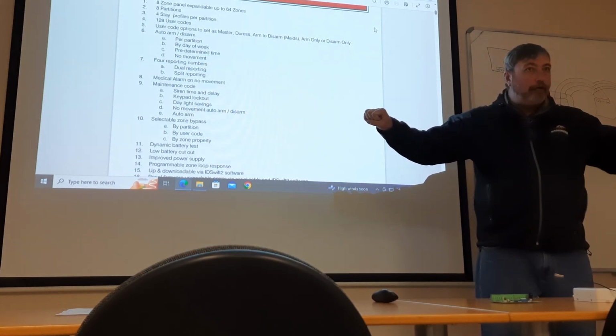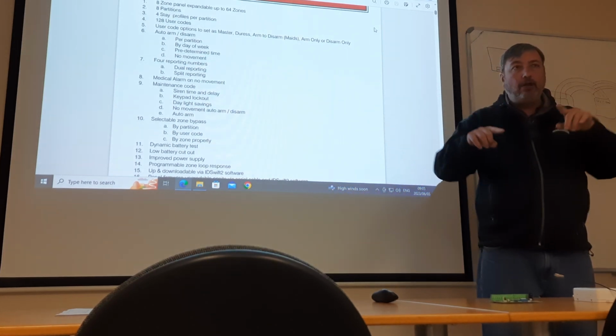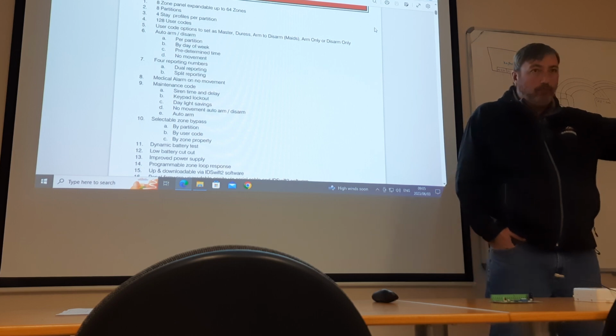So now you can have 3 keypads on the main panel: the one keypad will be for partition 1, the second keypad for partition 2, the third keypad for partition 3. And those guys can arm their partition separately from the others, when they go away earlier or when they come in earlier and stuff like that. That's another example where you would use it.